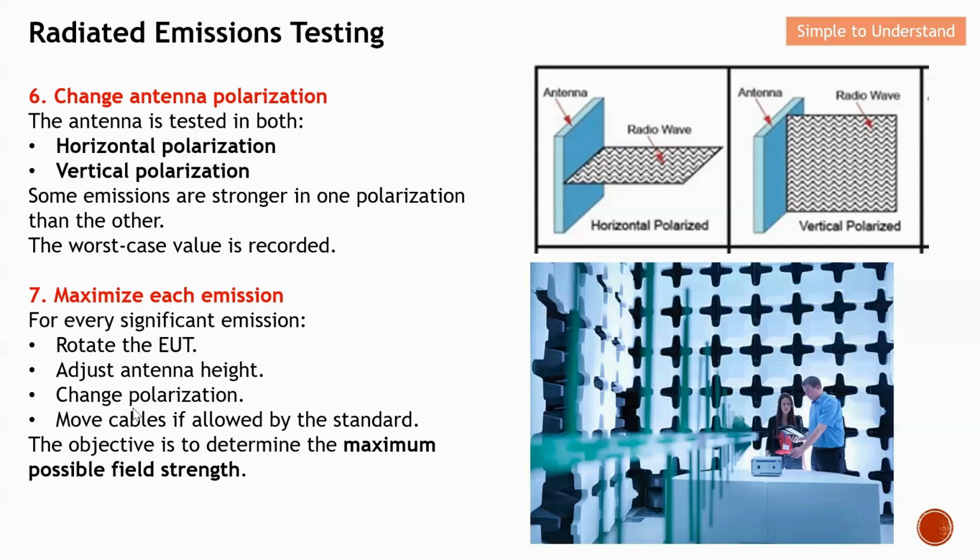Next, move cable if allowed by the standard. Basically, for example, there are different cables. You need to standardize how you want to place the cable. The key objective is always to determine the maximum possible field strength that is released by the DUT.